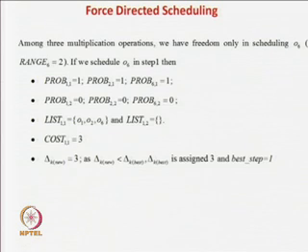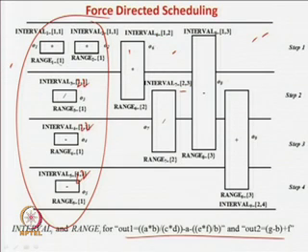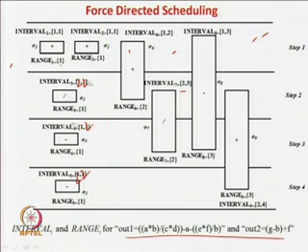Next we are going to see what your list is. If you look at it, what will be your list over here? In this case the list will be multiplier, multiplier, multiplier and subtractor. What will the list be over here? It will be divider, multiplier, divider, subtractor. This way you can find your lists. Now we will go for optimization one step at a time. So this we have found out. Now we are going to take one operation at a time. What do we mean by one operation at a time?